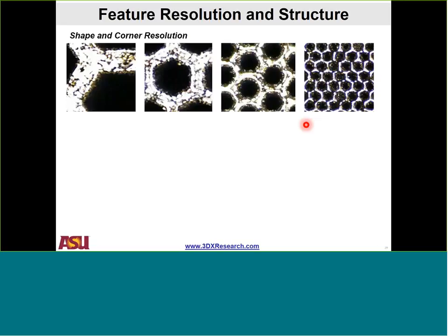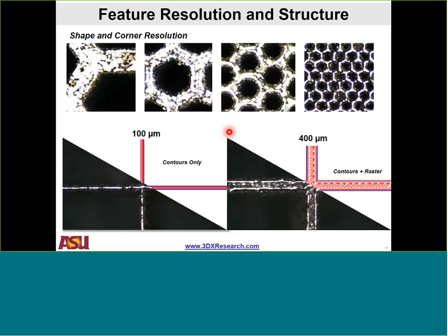So if you're relying on CAD geometry and software to make predictions, or if you're relying on hand calculations to describe behavior, it assumes certain things. For example, it may assume that you have sharp corners, and not that your honeycomb is starting to approach a circle. For those of us that make predictive models, we stumble with this, because when our analytical solutions or our finite element solutions don't match experiments, one of the reasons is this: the CAD model that we started with is not an accurate representation of the feature and the geometry that we end up 3D printing.